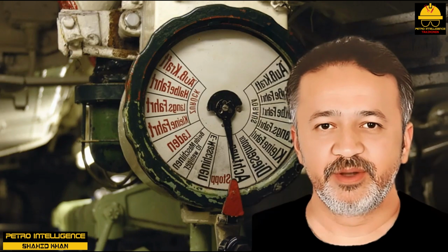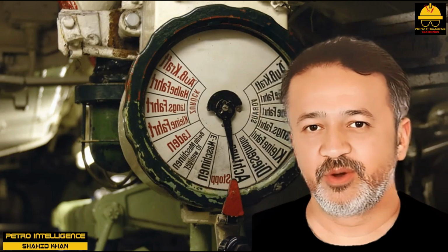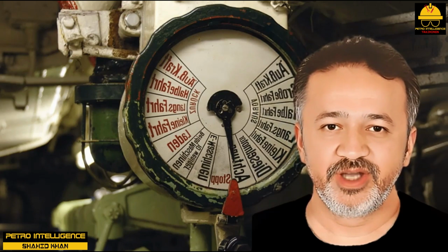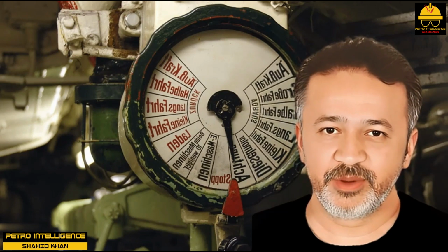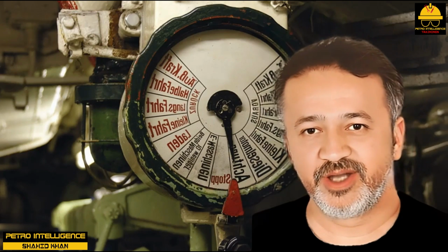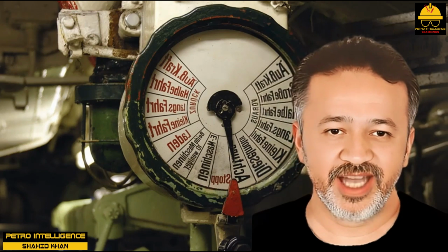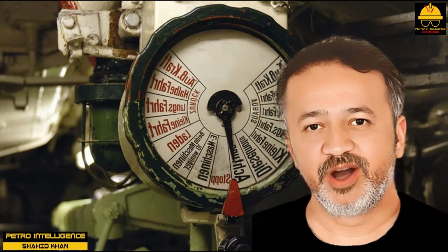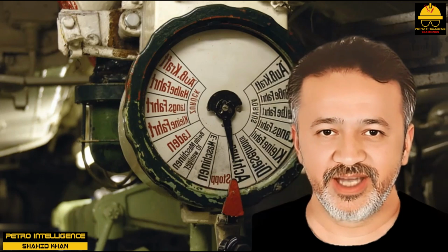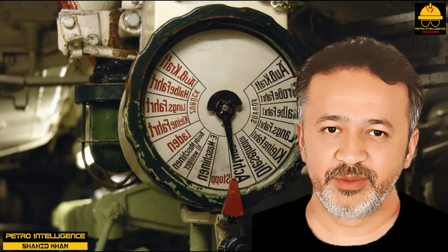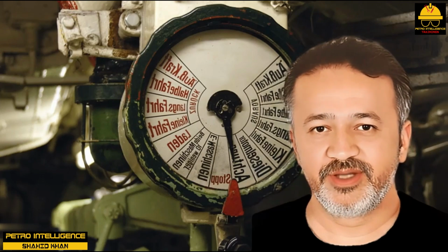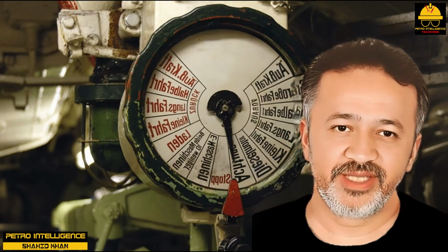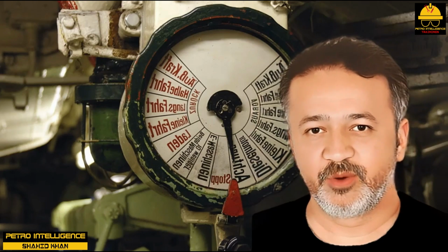Automation enhances the ability of a process operator to control large and complex process networks. The basic instruments include gauges like pressure, level, temperature, and flow, differential pressure, DP, cells, transmitters like pressure, level, temperature, and flow, controllers, pneumatic and electronic, transducers, control valves, and primary elements and sensors, displacer and buoyancy float, thermocouples, orifice plates, etc., and computers. The most common type of pressure element is a Bourdon tube.